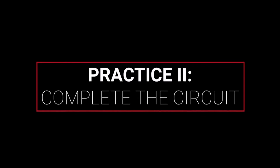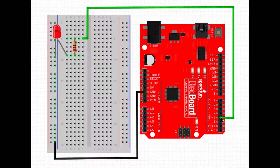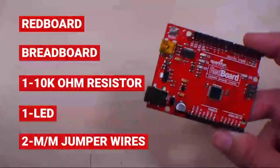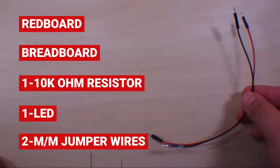Now that you've become familiar with some of the basics of coding, we're now going to jump into our first coding activity. For this activity, we'll be going a step further from our circuits and electricity video by changing the jumper cable connected to the 5V pin and moving it to a digital pin. For this activity, you will need one breadboard, a 10K ohm resistor, one LED, and two male-to-male jumper cables.